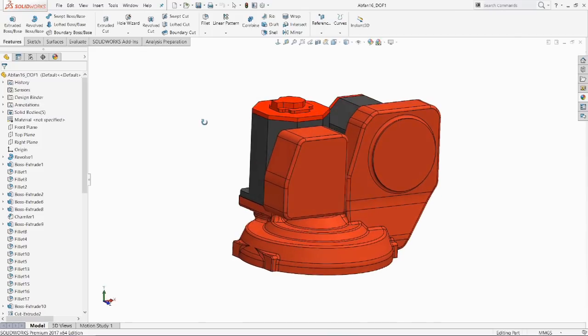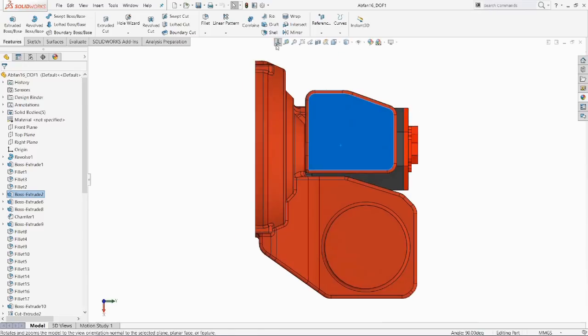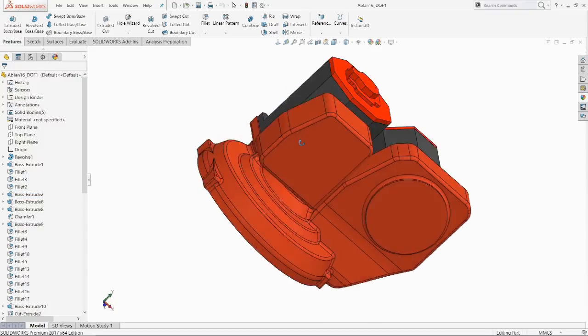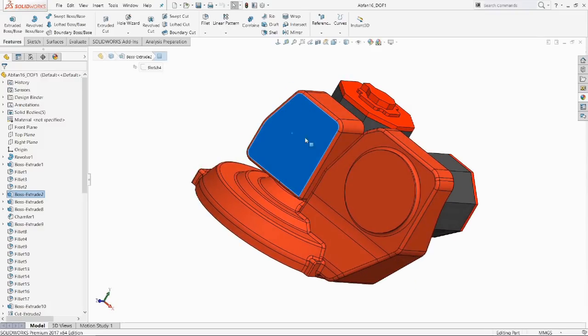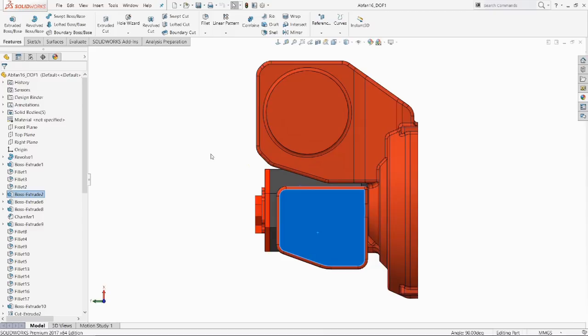Now, how about this? I pick the face, and now that other face there, that's what I want to be up. So pick those two faces, then hit normal to, and now that's going to be the face that's up. So orienting the way your model goes normal to. Just pick a second face using the control key, and then hit normal to. There we go. All right.